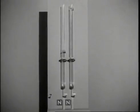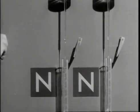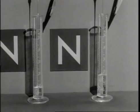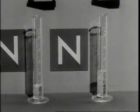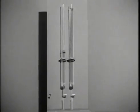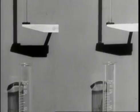These are two identical burettes containing the same Newtonian fluid. The pressure head in one is twice that in the other. The ratio of rates of flow is also 2-to-1, as we expect from Poiseuille's law. But if we charge both burettes with the fluid exhibiting nonlinear behavior and apply the same ratio of pressure heads, the result is quite different.